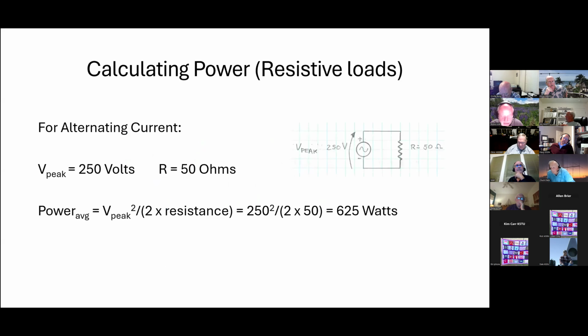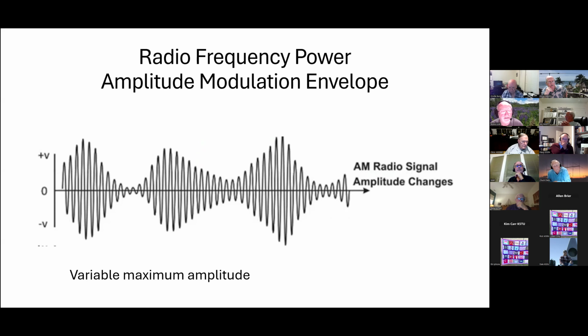And if you're looking at waveforms like this, if this waveform were constant, just the regular old RF watt meter will rise up and pick this level eventually. The problem with things like sideband is, can it follow this change? And that's why your old watt meters would read something lower than your peak envelope power, because the inertia in the meter, the physical meter, could not follow it. Right, it just couldn't follow it.